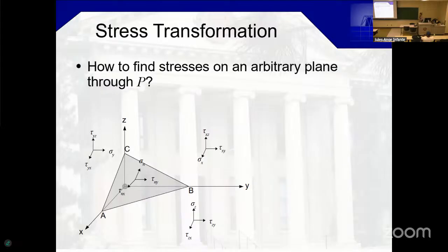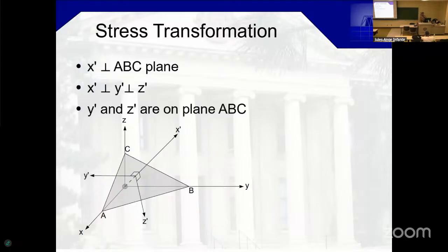So we said that the stress tensor is a matrix that represents stresses at a given point. And because it represents the stresses in all the principal directions, with the shear stress and the normal stresses, it represents the entire state of stress. So I can now interrogate that matrix at any point and ask for the stress in a specific direction that may be of interest to me. Very often we ask for the principal ones, but it's not always the case.